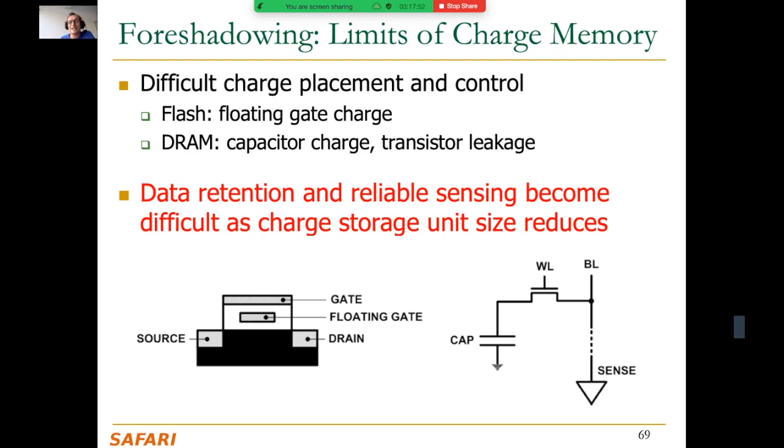But there's also another thing that's really interesting here. A lot of the things that I'm telling you about are really fundamental. They're not just specific to DRAM. Some specific incarnations may be specific to DRAM, but the high level, like charge leakage, randomness of retention time, how to solve the problems, are very fundamental to other types of memory, and they're going to recur in other types of memory. One example is flash memory. So even if DRAM goes away, these problems will not go away.